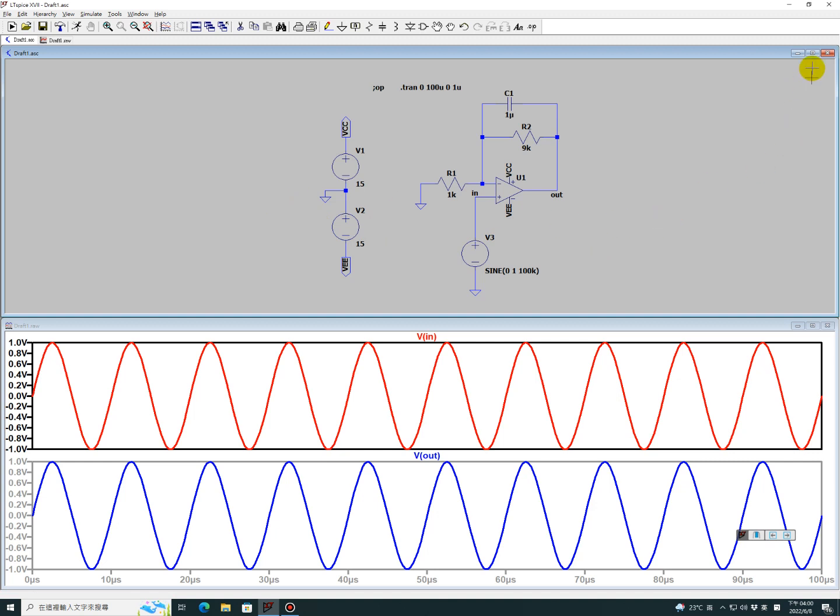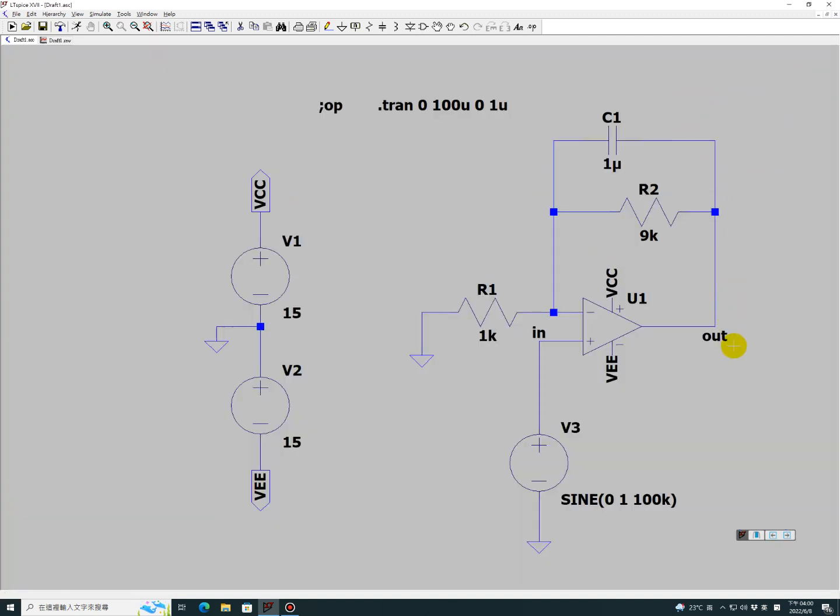And of course, if I want to check what the output limit current can give you, what kind of effect you can have, then I will put a load resistor here. We note the current will limit the output. So now for 10 volt, if I give you like 10K, then 1 milliamp. If I give you 1K, that's 10 milliamp.